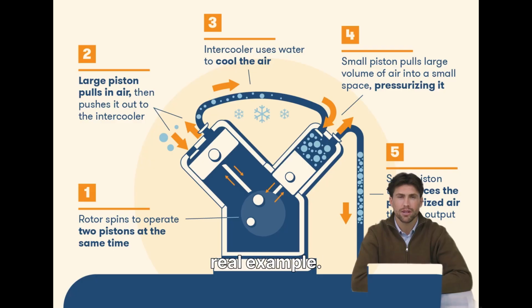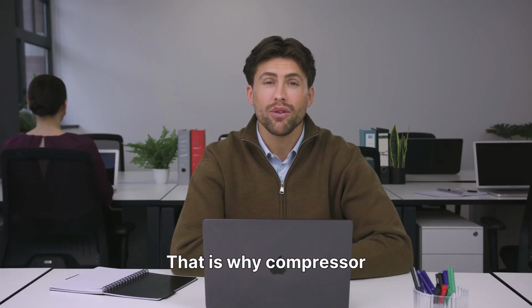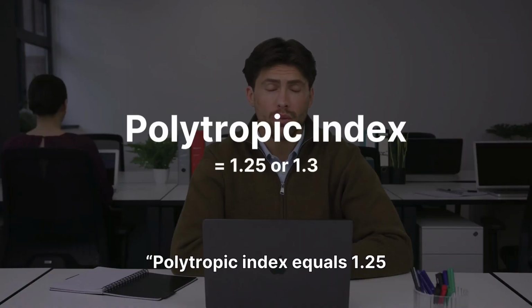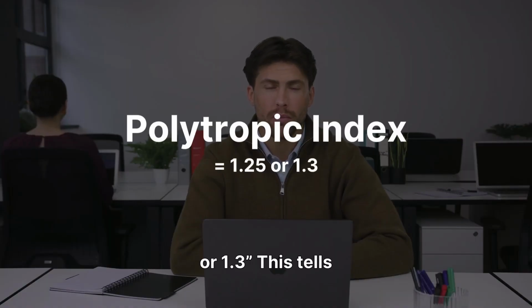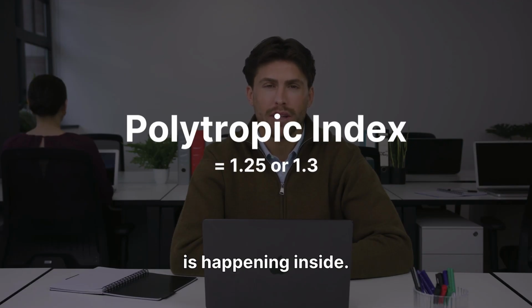Now let's take a real example. A compressor. Air enters at low pressure. Air is compressed. Temperature increases. Some heat is lost. Some heat stays inside. So is it adiabatic? No. Is it isothermal? No. Then what is it? It is polytropic. That is why compressor companies always mention polytropic index equals 1.25 or 1.3. This tells engineers how real compression is happening inside.